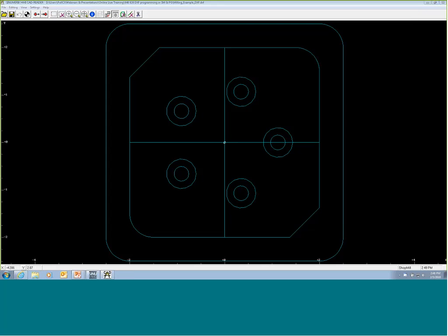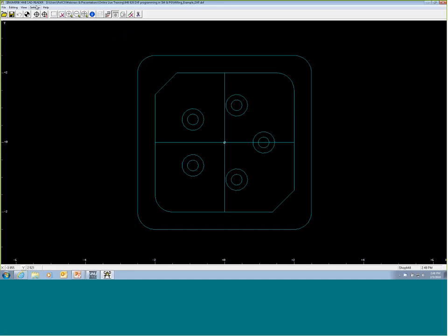Okay. So in this case, we're going to create some holes. I do need to go to Settings and select Drilled Holes. That's important, and that's going to change my hole strategy here. Now, the way the holes work, I can get it through a pull down. We can do drill pattern here and pick these holes, or by clicking on the first one to the left, that's the start hole, and then I'm going to end my holes.